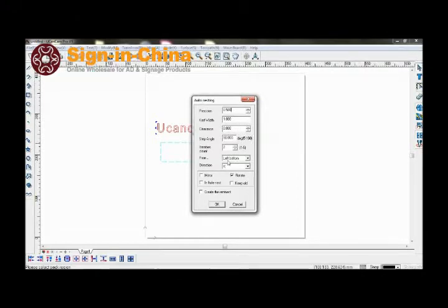You can choose the direction that it will nest from and which way it will go. Mirror will automatically mirror the object in an attempt to save material. In-hole nesting will nest some of the objects within any space possible. Keep old will keep the original object.